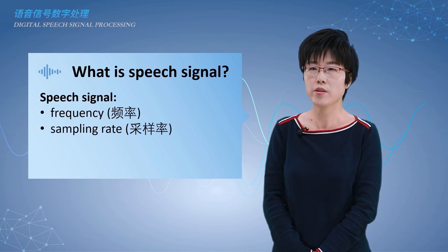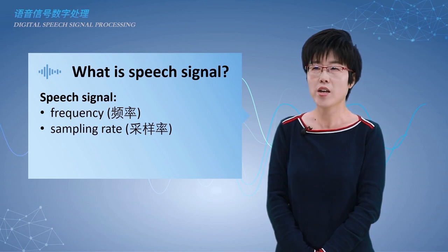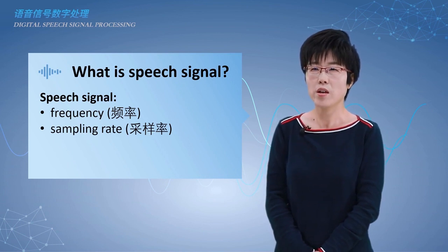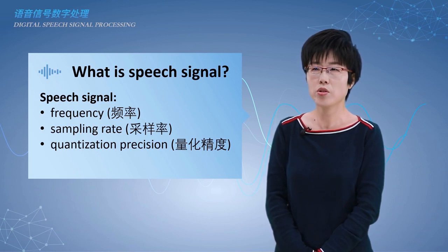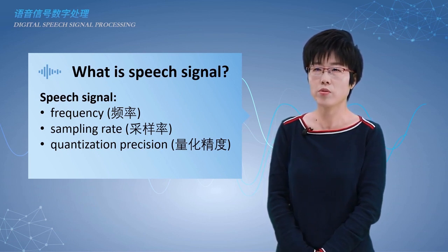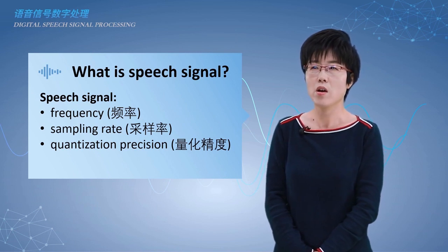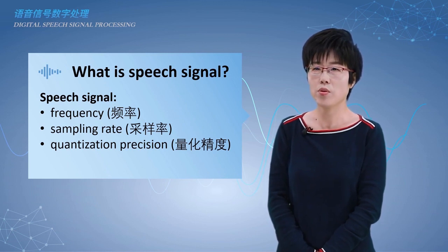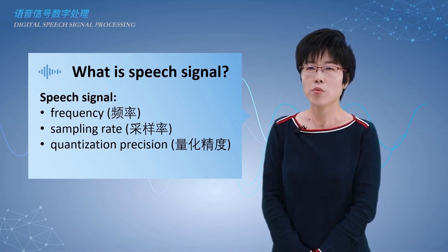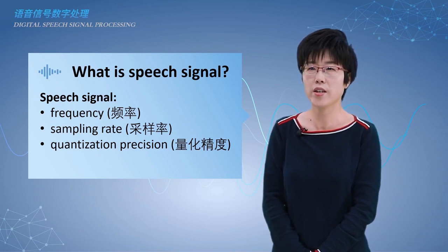Nyquist sampling rate is the lowest sampling rate that will permit accurate reconstruction of a sampled analog signal. Quantization replaces each sample real number with an approximation from a finite set of discrete values or levels. Quantization precision is the base allocated to each sample, leading to a number of different levels. The more levels a quantizer uses, the lower the quantization noise power is.